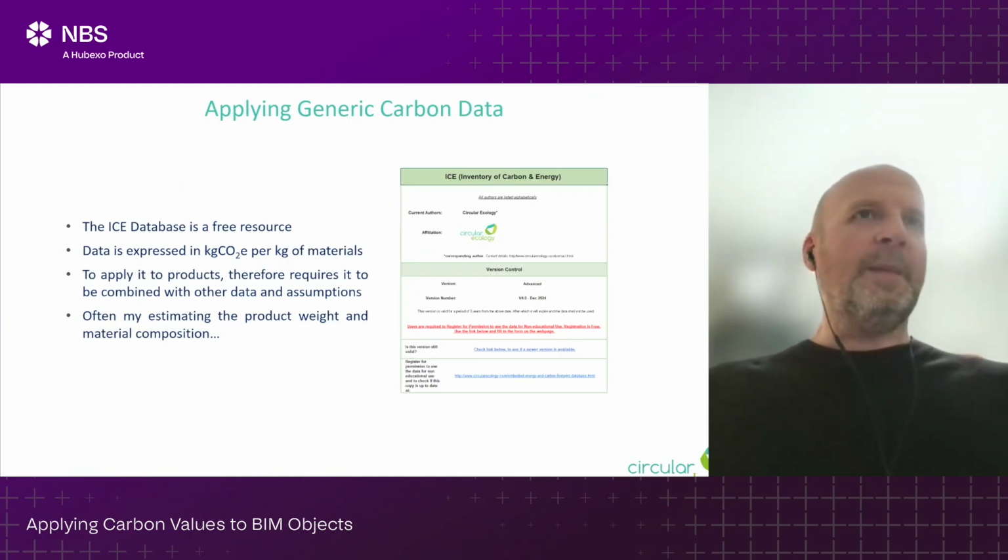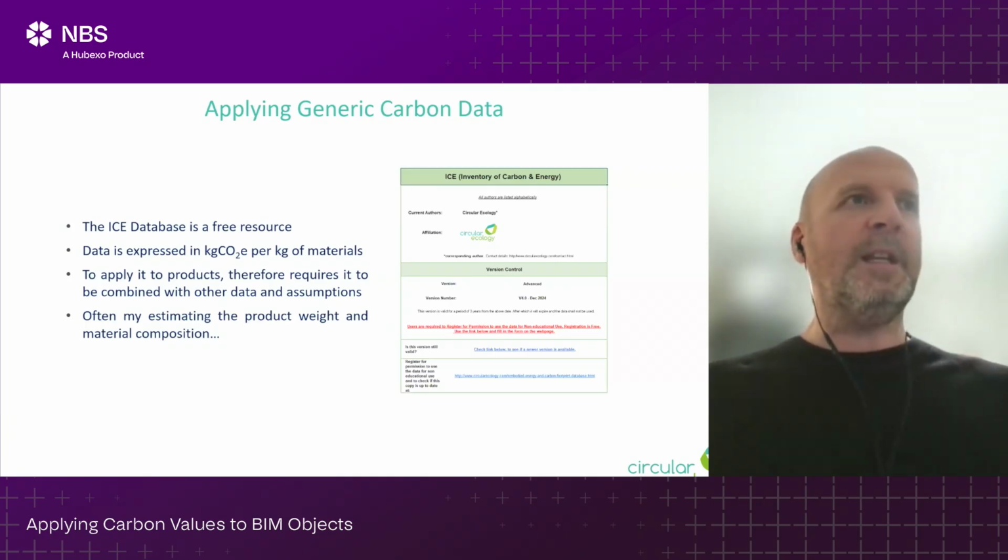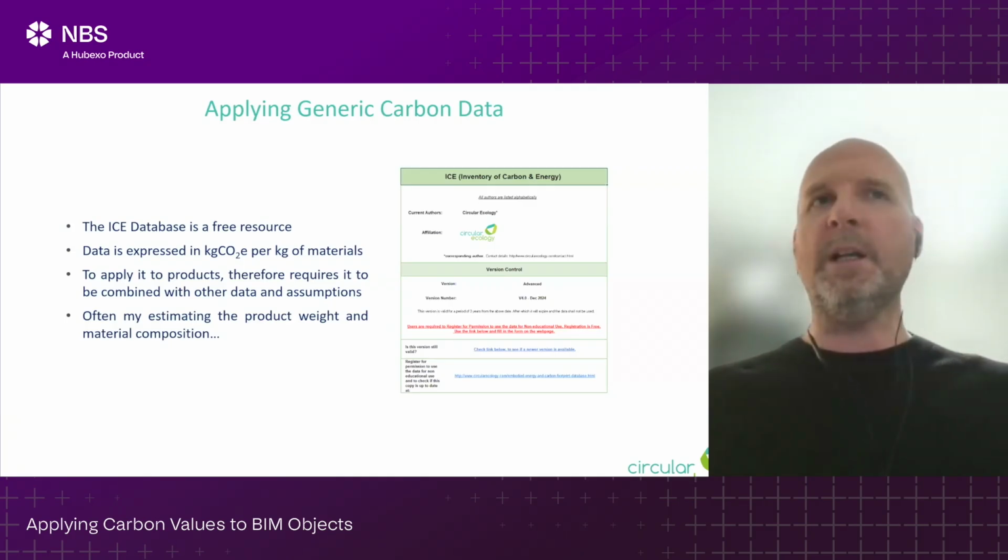Now, the ICE database, just in summary, is a free data resource. It's downloadable from the Circular Ecology website. The data is expressed in kilograms of CO2 per kilogram of materials, so you can apply it to your products.